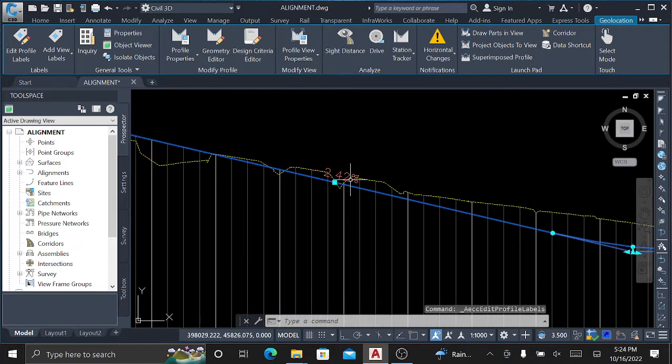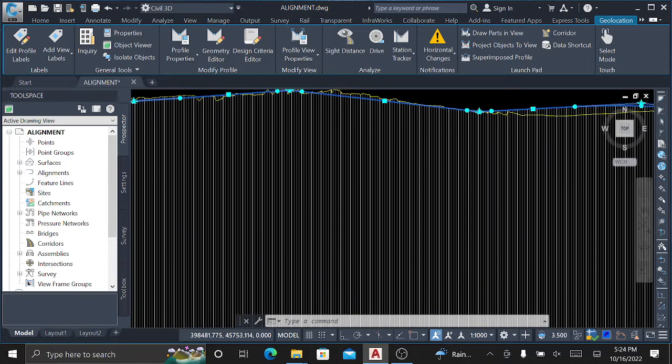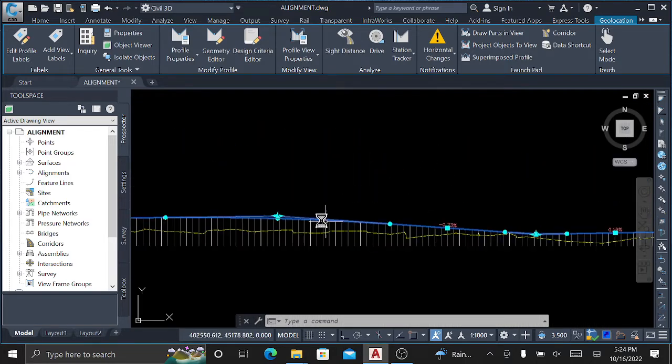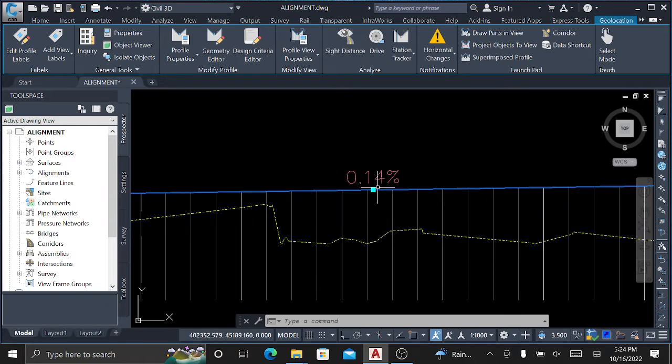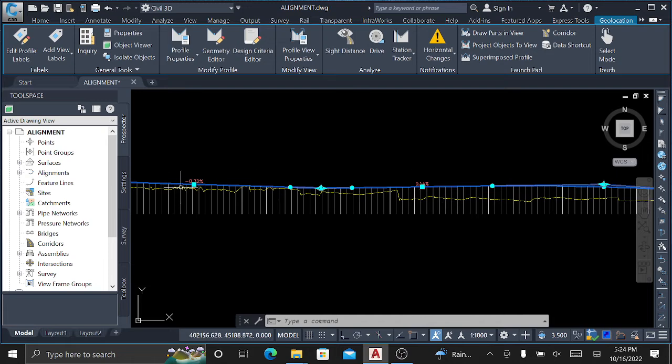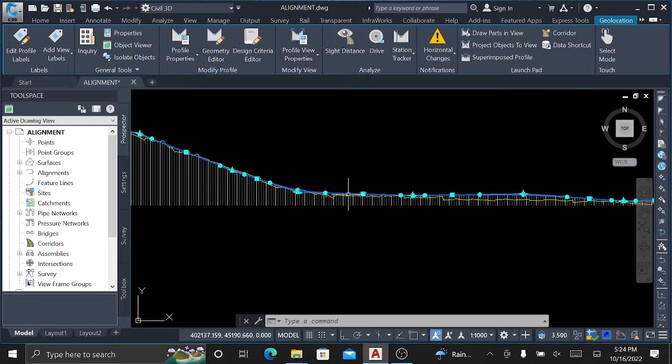So that means that for a certain area where you're expecting to have a flat area, for example, for this area, you expect to have a grade less than 4%, right? So once you look at your grade and it's beyond 4%, then you understand that you're conflicting with the design parameters.